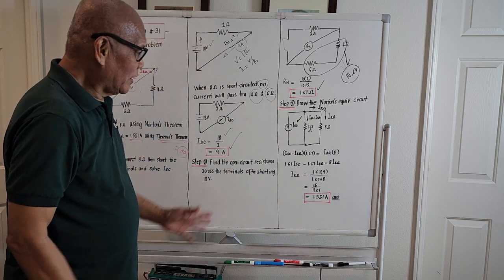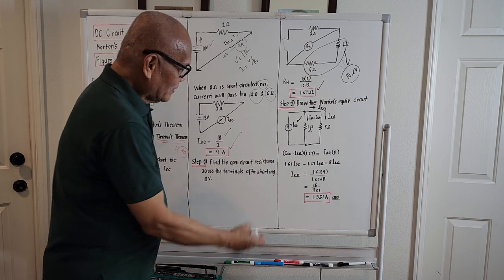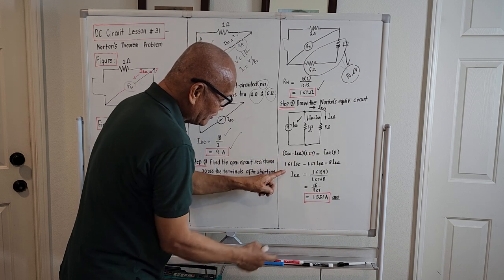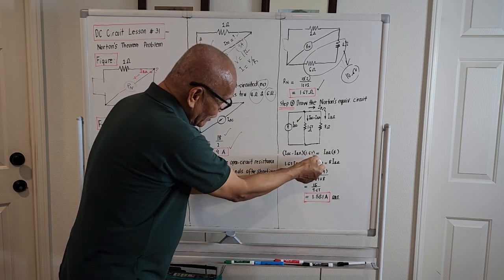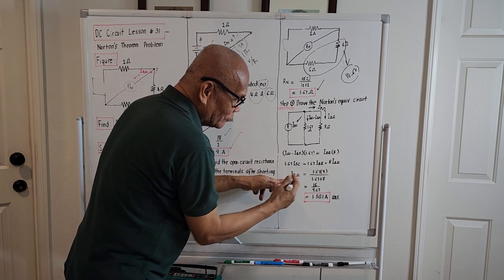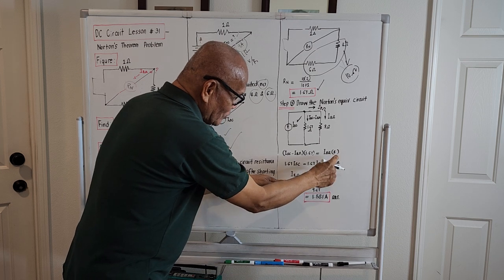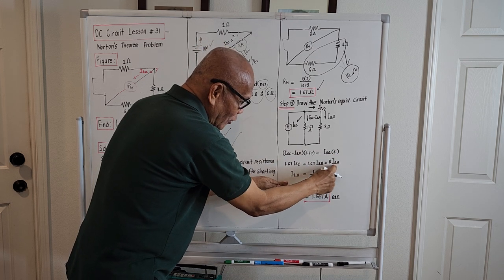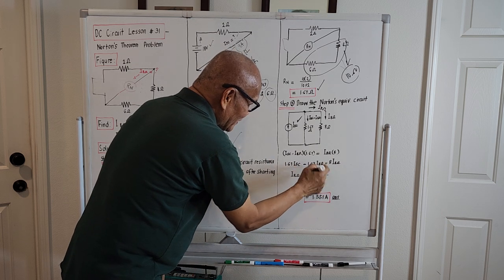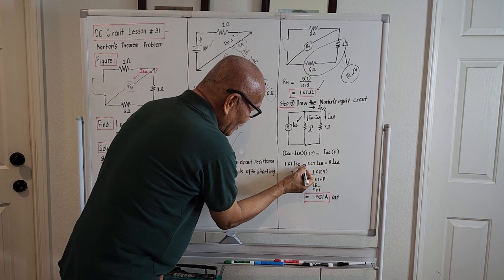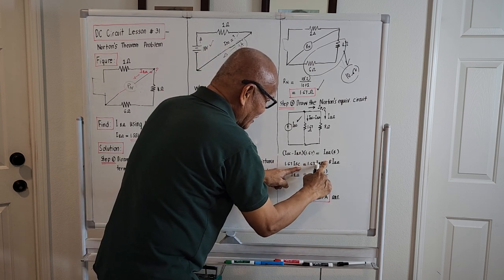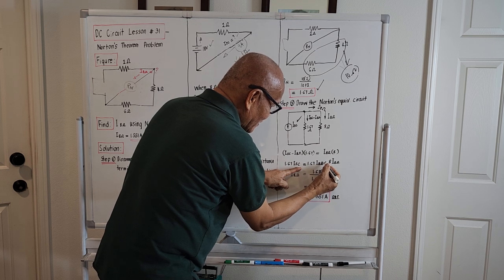Okay? And if we try to simplify this, this is now just pure algebra. I short circuit times 1.67 is this one. I sub 8 ohm times 1.67, this is now negative. And this should be equal to the right hand side, 8 times I sub 8 ohms. So if we transpose this to the right, we put this negative to the right, so they will now be similar terms.